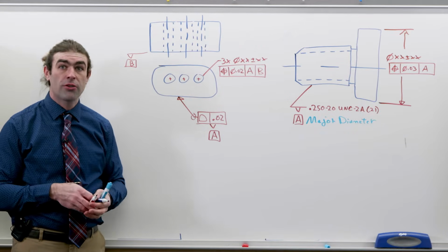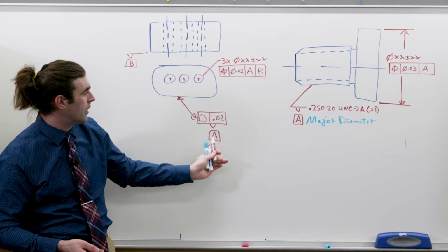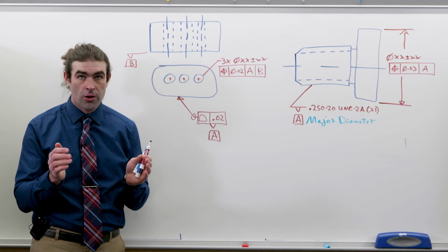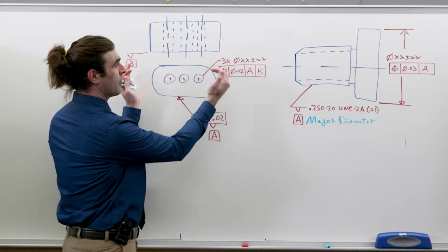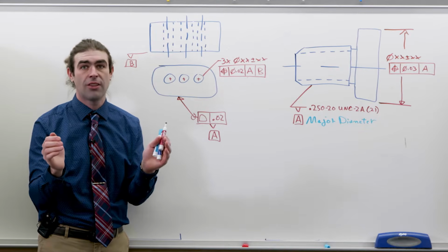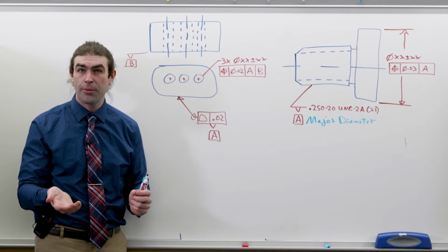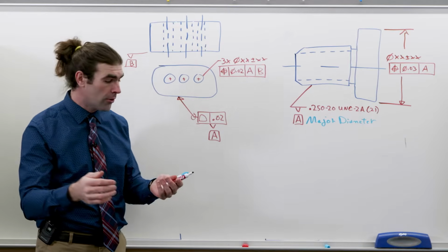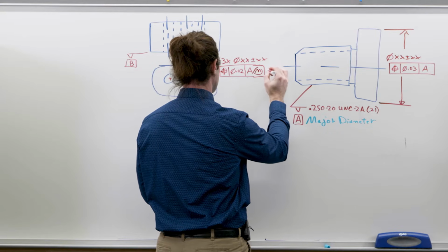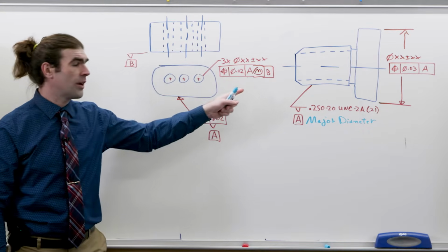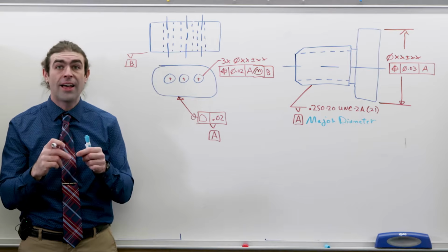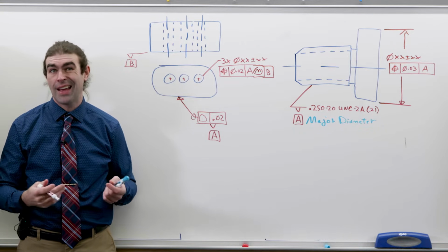The reason being, what you're telling the inspector, if you do this as a primary datum, in order to have a true geometric counterpart at RMB, you'd have to have a perfect opposite shape, so an internal slot that collapses at the same time to catch the high points. That kind of stuff is possible to produce for inspection, but generally, unless you have a really good reason not to, you want to specify that at MMC or MMB so that they could make a slot shape, drop it in there, and then check the position as normal.